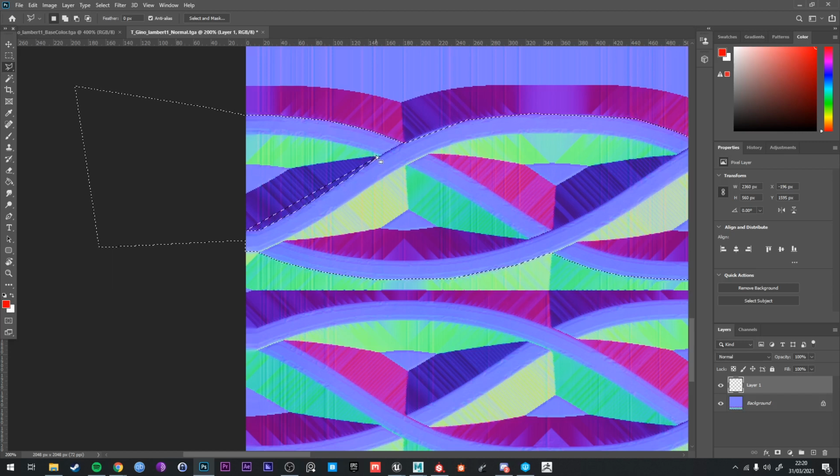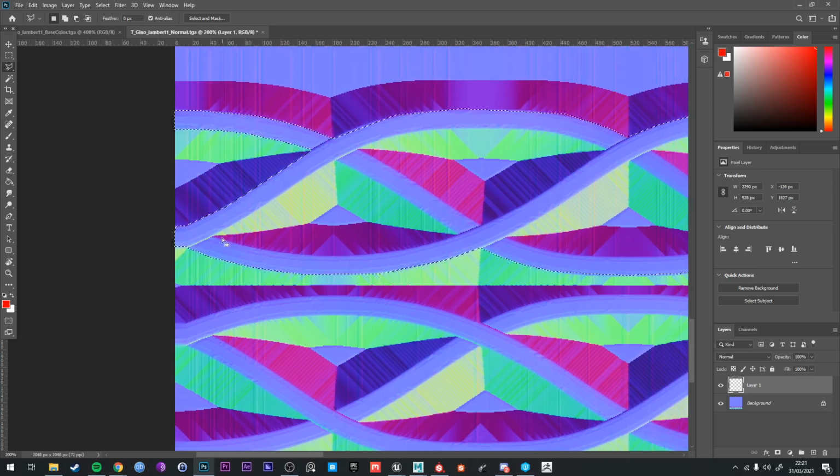Okay, getting there slowly but surely. Misclick. Feels bad. What you'll also notice with the dilation is that it can kind of make up for any points where I don't go quite up to the edge with my mask, right? Because the dilation is going to bleed the brass material outwards into the space where there's no mask.